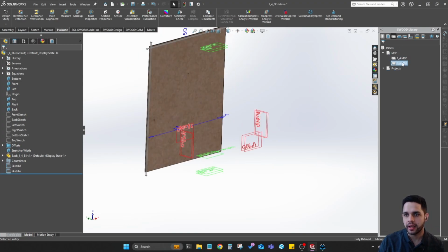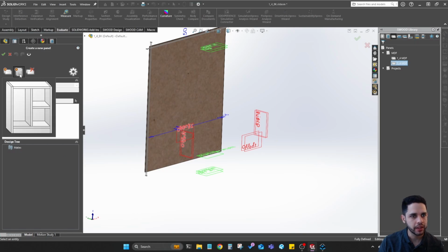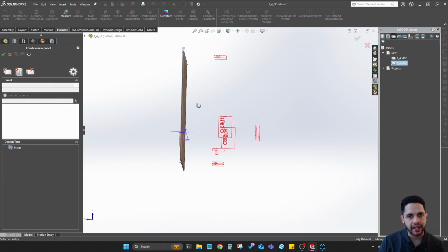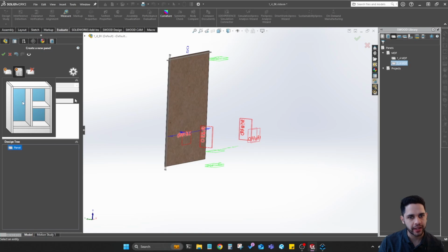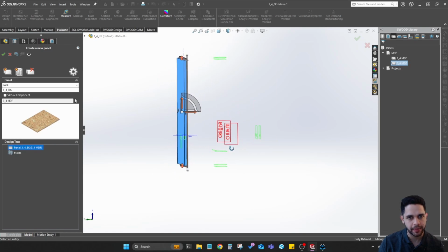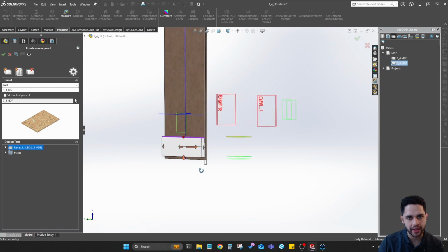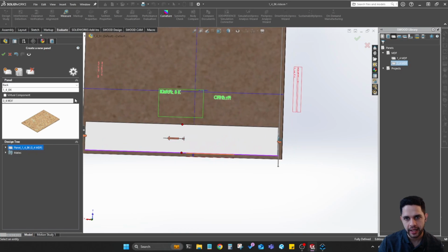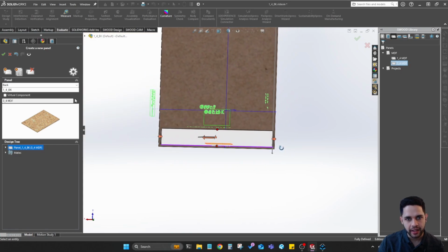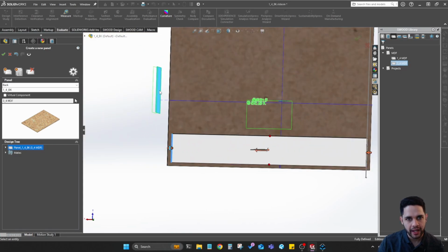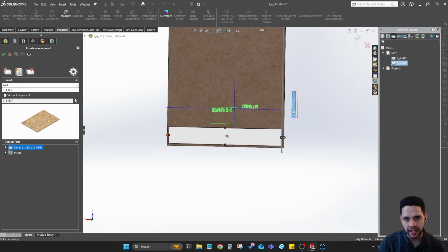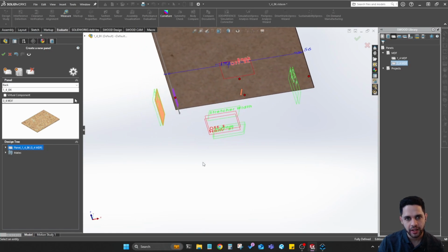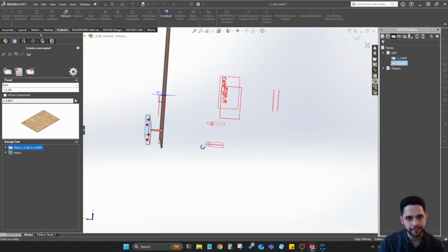Come in, click on our 3/4" MDF panel, insert a copy, click on new panel position, and this is going to be towards our back, so we want to click that back panel. As you can see, that's back there. We want the top attached to that stretcher width plane, the bottom attached to the bottom plane, and then the right and left sides mated to the standard left plane and right side plane.